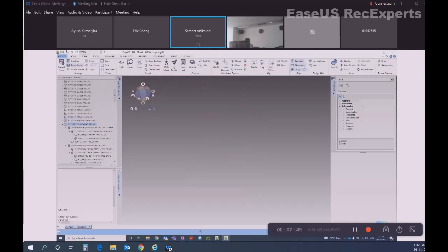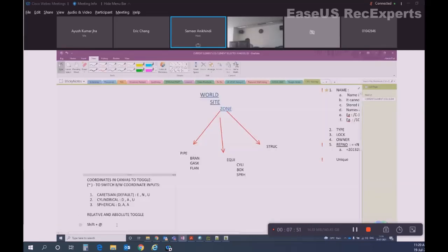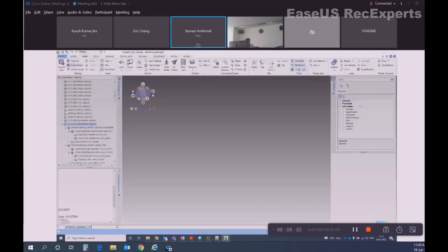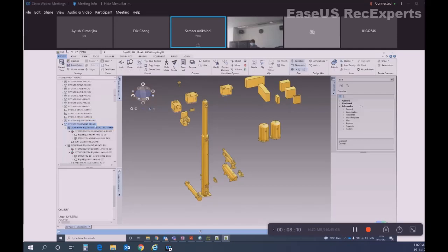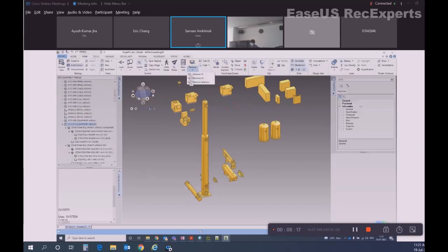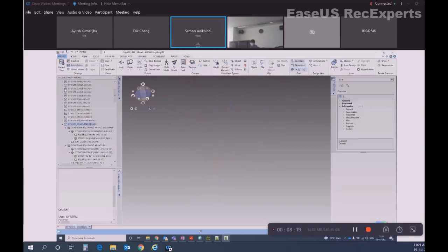The combination for removing all is Alt plus V plus V plus E. This is very frequently used, Alt V V E. Whatever is there in the draw list, it will remove quickly. Instead of removing items one by one, just use Alt V V E. It will remove everything.